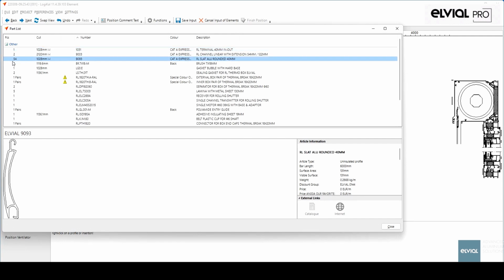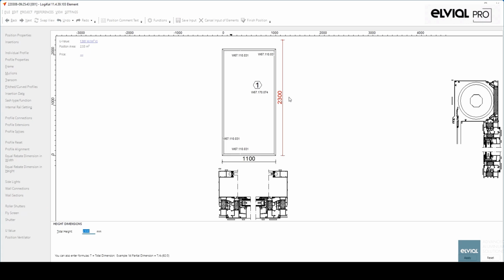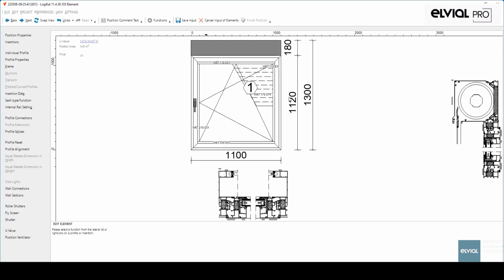It's important to know that since this is an extra function that affects the roller shutter after our selections, the software can't make suggestions about the housing and the handling. So the user shall be extra cautious when using it, as we might end up with a shield that can't fit in our housing. Now let's shorten the window, and see how this will affect the housing and the handling selection.